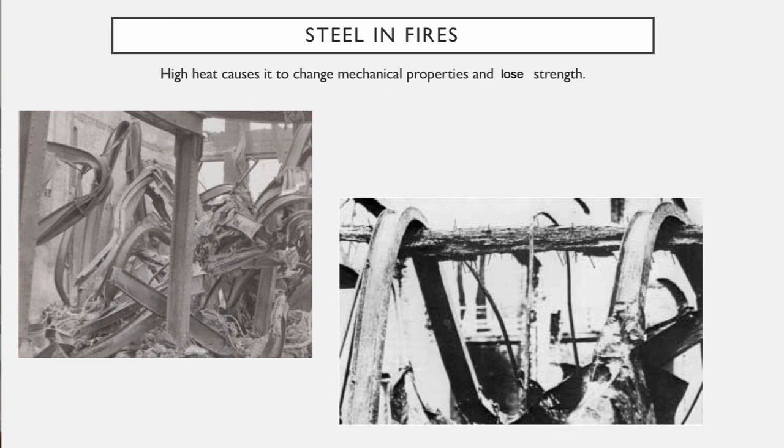And interestingly enough, here's an older photo, and you have a very large wood member. Very large members of wood in high heat tend to char on the outside. That char creates a protective coating, and it takes much longer for them to burn. And here you have the remnants of a charred wood beam still carrying the deformed spaghetti-like steel beams that used to carry the structure.